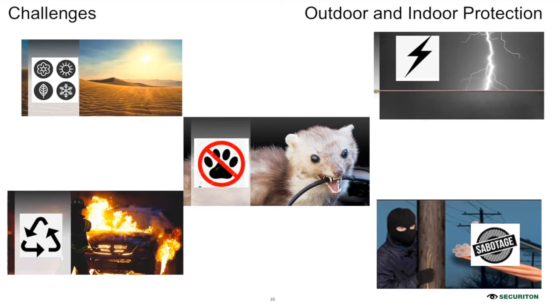In terms of animal vandalism, as you know, sometimes it's in the middle of a desert, and it can be somewhere where animal problems will be there. As you know, our detection system is made of copper or stainless steel, so we should not have a problem with animal vandalism. And in a real fire incident, as you know, in most cases this is crude oil we're talking about. As I mentioned earlier, if a fire happens, it takes 21 hours to extinguish.